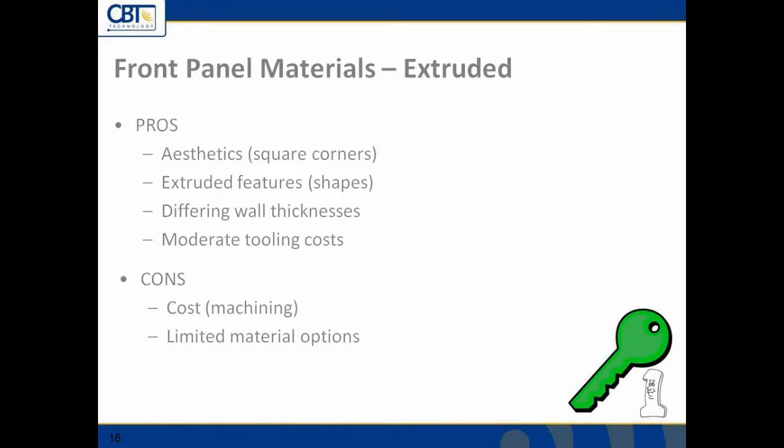As far as some of the negative parts, well, the cost of those parts to manufacture as far as the cutouts, the I/O cutouts, connectors, those types of things, the machining process that has to happen in smaller volumes can somewhat be prohibitive to some. Higher volumes, we get into punching and stamping, so we can eliminate a lot of that. But most of the volumes are usually into the machining area.